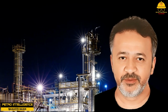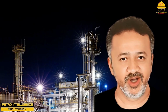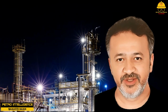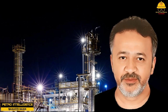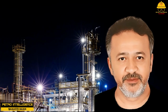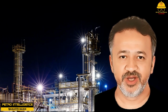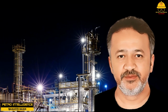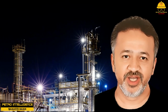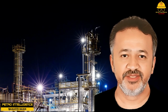Process technicians are responsible for establishing correct flow or feed rates to the reactor, ensuring correct temperature, pressures, and level, monitoring and controlling reaction rates and time, ensuring that specified mixing or agitation is occurring, and monitoring and maintaining auxiliary equipment. Reactors combine raw materials with catalyst, gases, pressure, or heat. A catalyst increases or decreases the rate of a chemical reaction without becoming part of the final product.